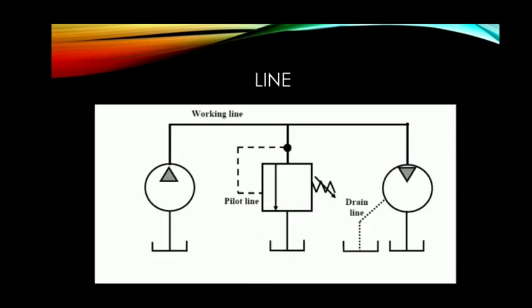Lines. Pipes, tubes and hoses, along with the fittings or connectors, constitute the conducting lines that carry hydraulic fluid between components. Lines convey the fluid and also dissipate heat. Lines are one of the disadvantages of a hydraulic system that we need to pay in return for a higher power to weight ratio. They need a return path. In contrast, for pneumatic systems, no return path for the fluid, which is air, is needed, since it can be directly released into the atmosphere.